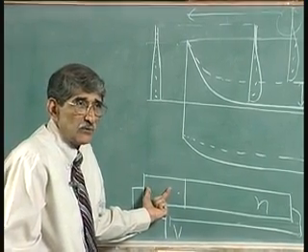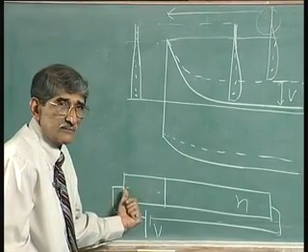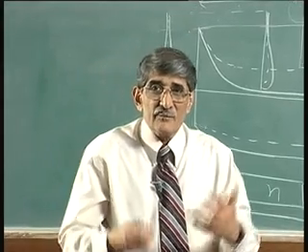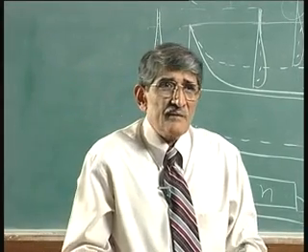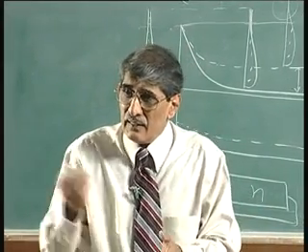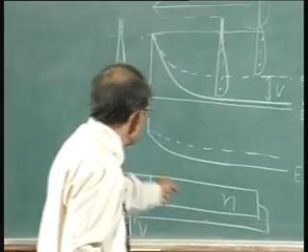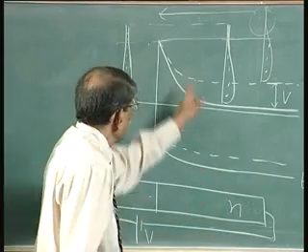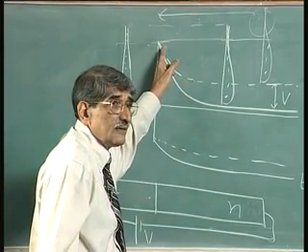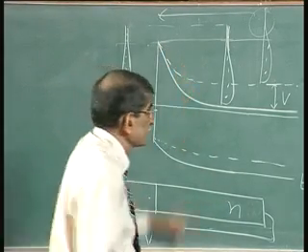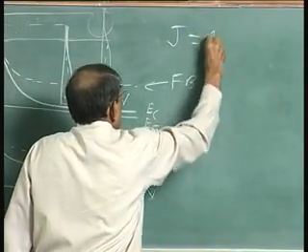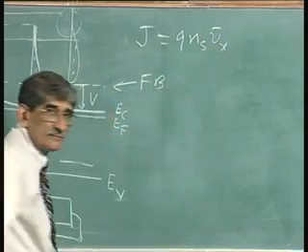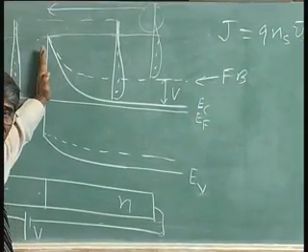will be able to take away those electrons, because the total electron concentration is very large, 10 to the power 22 if you have. Even a very small field will help to remove those charges which are injected to give rise to the current. Here you calculate it as J = q n into V. J is equal to q n of S into V x. That is when it is here.